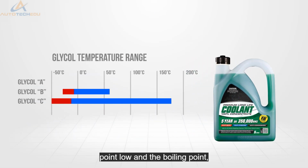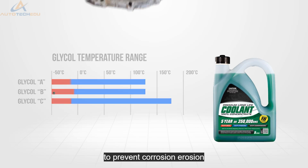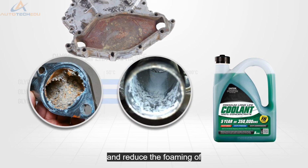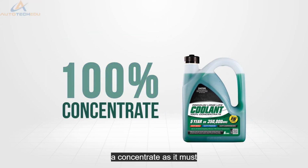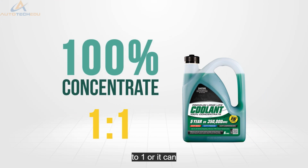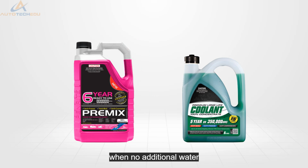Glycol keeps the freezing point low and the boiling point high. Inhibitors are used to prevent corrosion, erosion and reduce the foaming of coolant. Coolant is available as a concentrate, as it must be diluted with water up to a ratio of 1:1, or it can be supplied as a premix when no additional water is required.